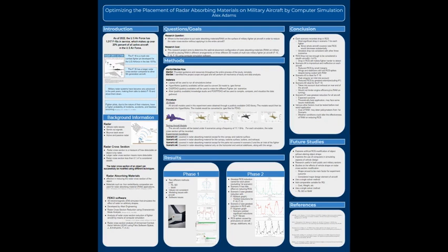Scenario 3 is ideal for the F-16, as it took the singular air inlet on the fighter into account and reduced the radar cross-section by the greatest extent, excluding the first scenario. Scenario 2 would be ideal for the F-15, as it takes into account the dual exhaust on the rear end of the aircraft, and it would not hinder engine efficiency, as there's no RAM on the actual turbine of the engine. Scenario 1 saw the greatest reduction for all aircraft, but this was the expected outcome.